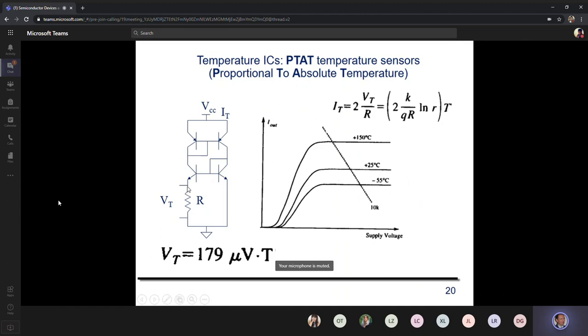And you are left with the difference of this point with respect to ground and the point on the right with respect to ground, this one, that is equal to this, that is the lower contact of the resistor. Okay, so by measuring the voltage drop across the resistor, we are actually measuring something that is the same as before.